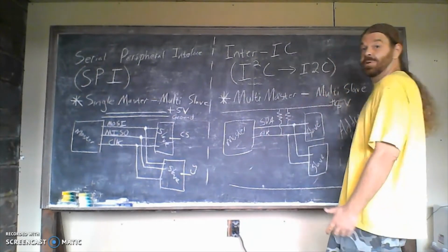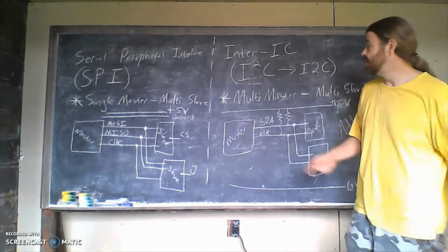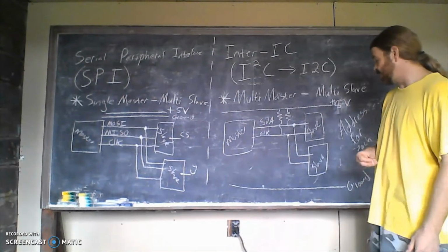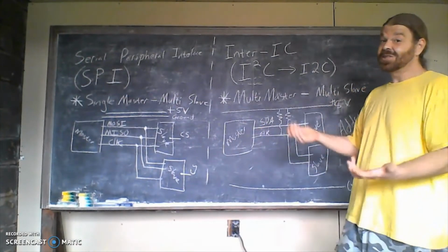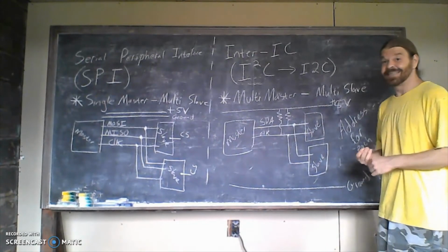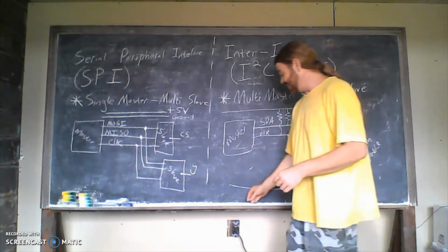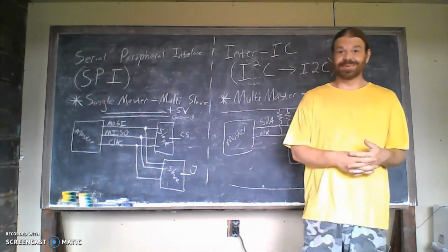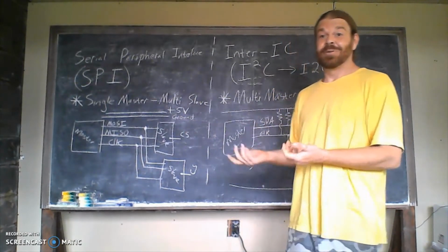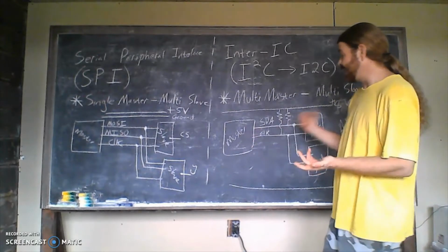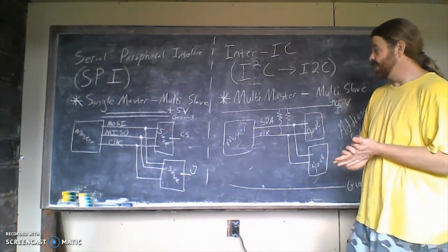And then the one whose address that is responds. So that's how I2C communication works. Only 2 lines to connect. Makes it super easy for connections, and a lot easier to sit down and solder 2 lines than solder a bunch. Everything's going to connect to that rail however many we have.